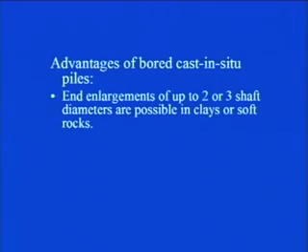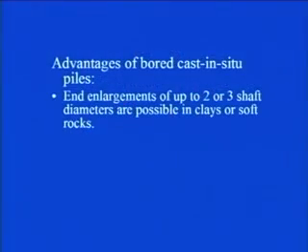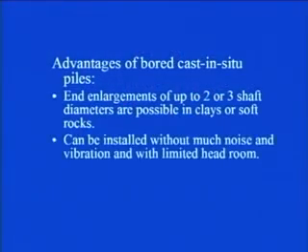See, in the earlier case it was for driven cast in situ piles, the enlarged base was able to form in granular deposit. However, in case of bored cast in situ pile, this end enlargement can be possible in clays or soft rocks. It can be installed without much noise and vibration and with limited headroom.